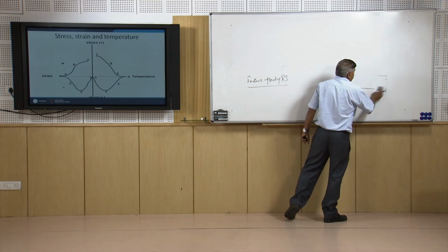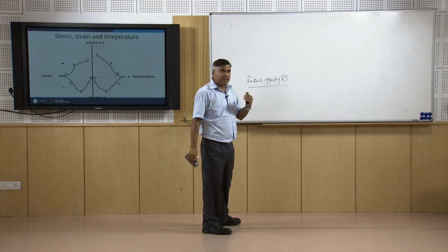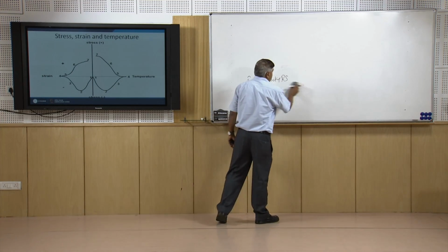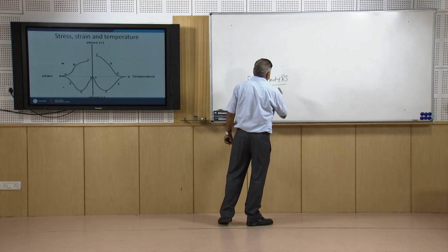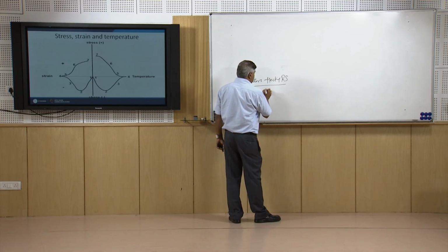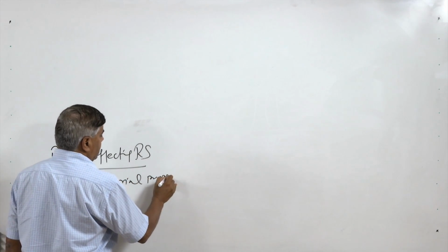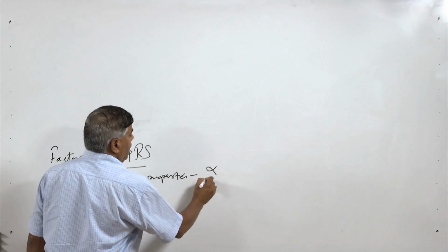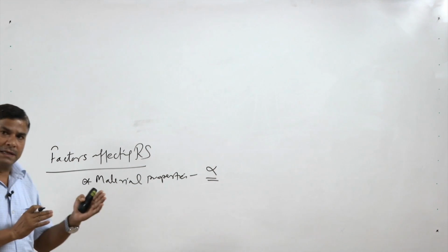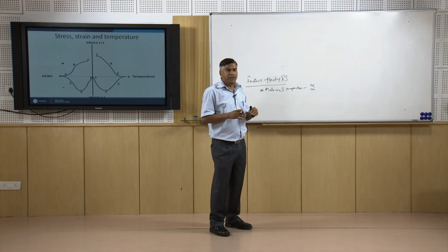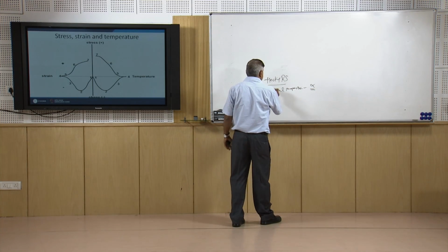So, considering this point, sometimes filler metal is intentionally selected in such a way that the yield strength or elastic limit of the metal is low, so that the residual stress magnitude can be reduced. Now, we will see the different factors that affect the residual stresses. One is the material properties, especially alpha, the thermal expansion coefficient. If the expansion coefficient of the filler metal, the weld or the base metal is high, then there will be more expansion and contraction, which will lead to higher locked in strain, and that in turn will cause a higher residual stress value.